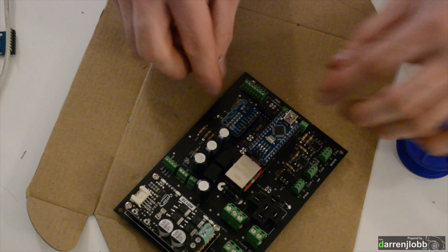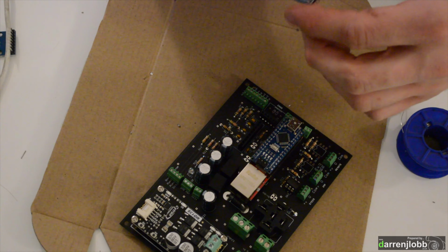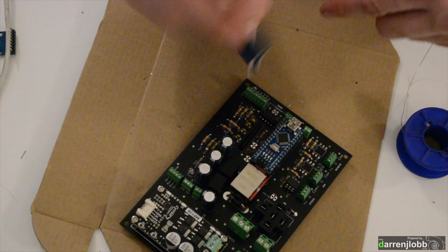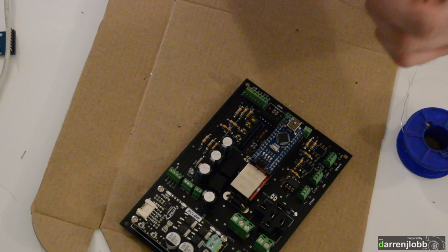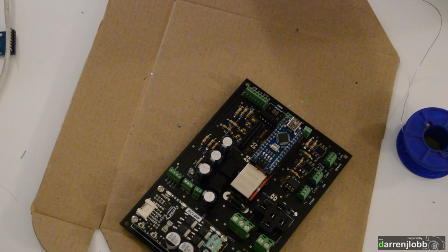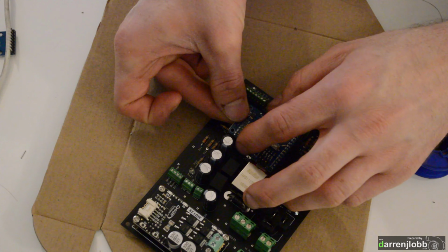like so. Also, I should have said that before I started, to make sure you have this the right way up before you solder that, because obviously you could put it either way and then your pin orientation would be the opposite way around. The way you want it, with the one I've bought, is with the writing on the top, but basically the ground and the power should be at that side of the board when it's in the board.